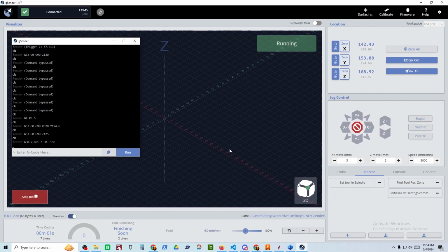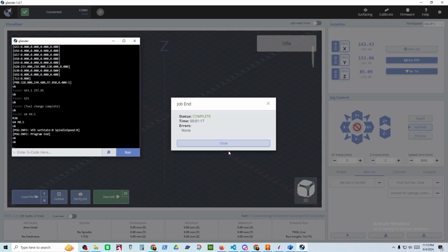It's pretty simple. Now I have tool recognition set up with our IR sensors, and the fascinating thing that we found was that by probing away from the switch, we can use the probe to actually check to see whether a tool has been loaded or unloaded properly. So the tool setter, I also have a touch plate and a 3D probe that we'll use here in a minute to find our part, are all wired to the same pin.